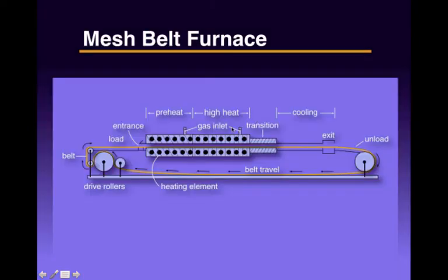For continuous production, you want to be able to keep loading parts at one end that need to be sintered, and there's a moving belt that goes around, and there are constantly emerging parts from that furnace. And so this allows you to program a certain production rate where the preheating, the heating, and the cooling down is all dialed into this overall cycle.